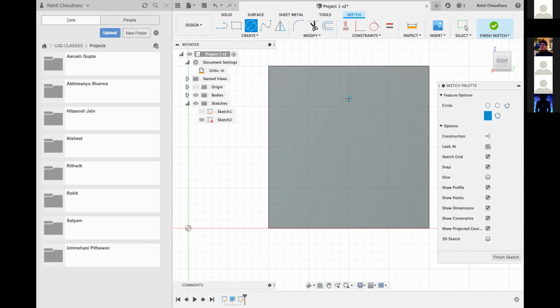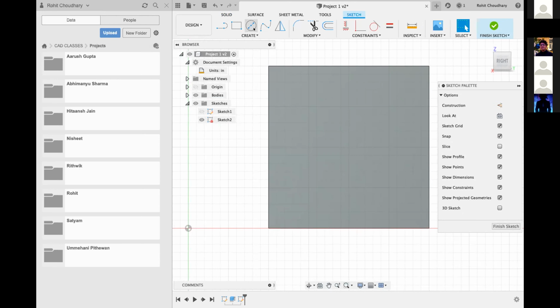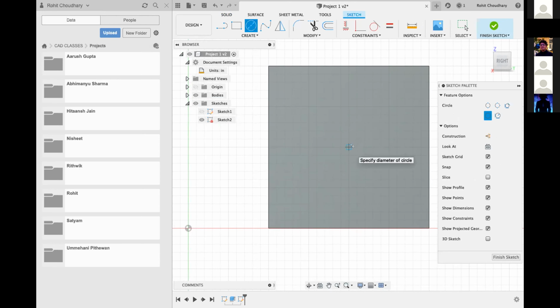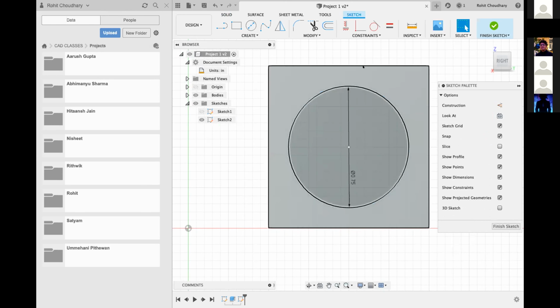It's different. You're not choosing one area and then dragging it. You're actually choosing the center point. So wherever you click, that's the center of your circle. Let's say we're going for approximately the center. If you use your grids, you can probably find it. And let's say we're creating 0.75, and that's going to be the diameter of your circle. Everybody knows what the diameter is, right? Yeah. Okay. So once you do that, just hit enter, and now you've got your circle onto your face.